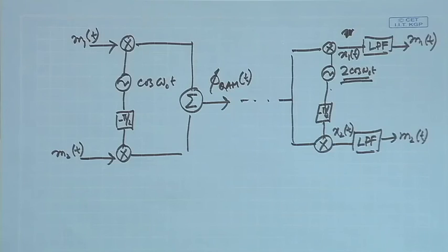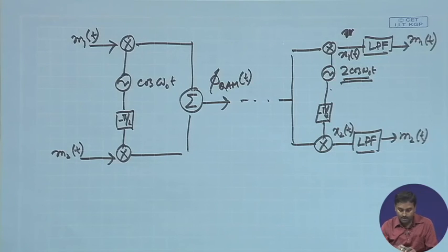But later on you will see that there is a carrier recovery process, because I am doing this demodulation coherently. There is non-coherent and coherent demodulation. Probably I have not talked about these terms, but I have been mentioning them. Non-coherent is like that envelope detector. That means I do not have to generate a local carrier which is synchronous in phase and frequency to the incoming carrier. So, that is called non-coherent. That means the receiver part is pretty simple and I do not depend on carrier generation. Whereas for coherent, my receiver performance will be subject to how good I am in generating the local carrier at the receiver.